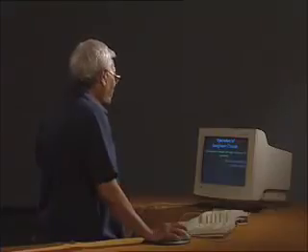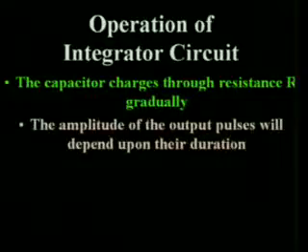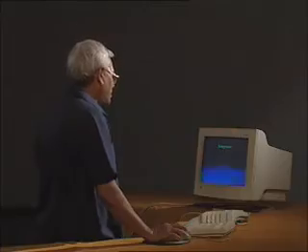What are the conditions for integrator? The output of the integrator will depend upon the duration of the pulse width and not merely on the amplitude. Therefore, short duration pulses can be eliminated, or any pulse which is of higher frequency, means short duration, as a noise can be eliminated here. Integrator.